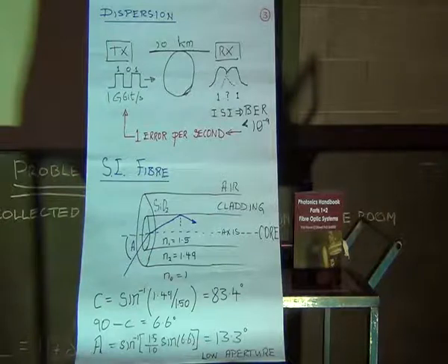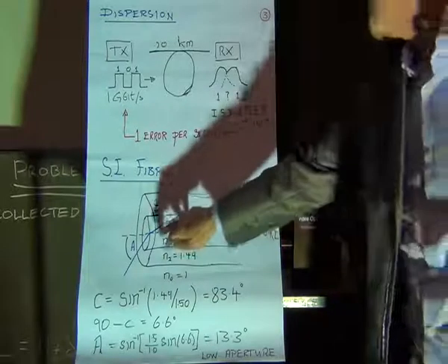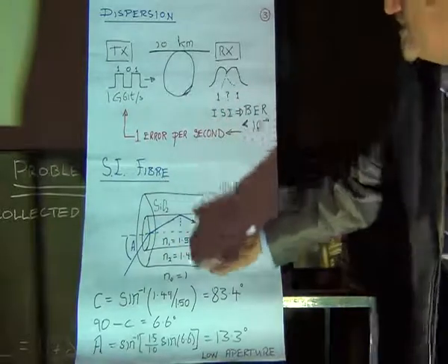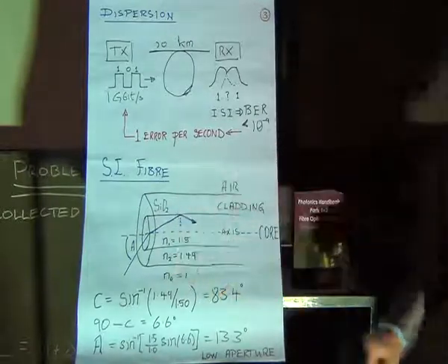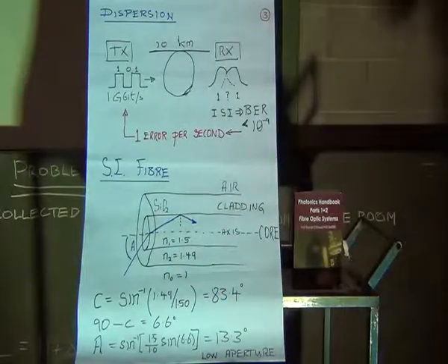Initially, we would have injected some boron or phosphorus or some dopant to slightly diminish the refractive index profile. So out in the edges, which we call the cladding, the refractive index there is 1.49. It's less than 1% lower. And that's all it takes to trap the light.